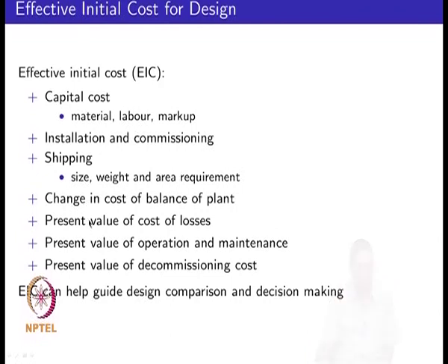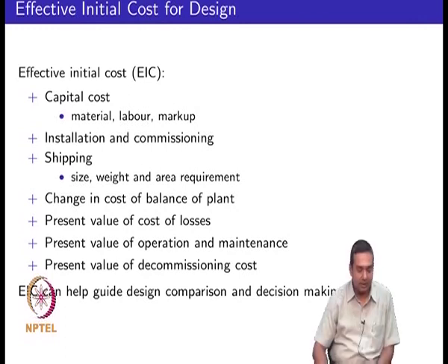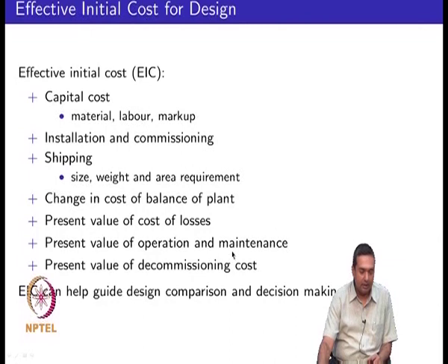There can also be other costs which occur when you run this particular power electronic system on an ongoing basis. For example, you might have operation and maintenance. You might have circuit breakers which might need periodic maintenance, the springs and the contacts might need cleaning. You might have capacitors whose ESR might change as a function of time. You might think about replacing the capacitors after so many years of operation. So those are future costs which have to be encountered when you operate your system.